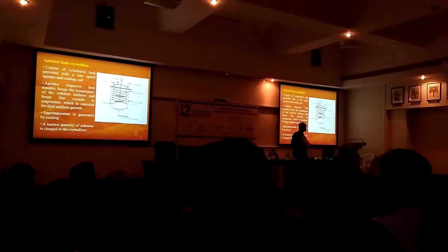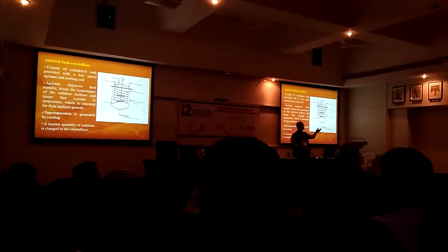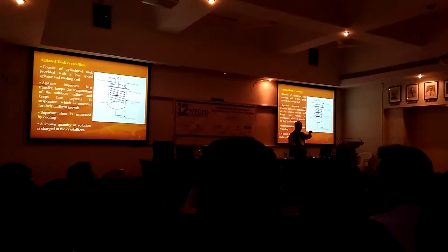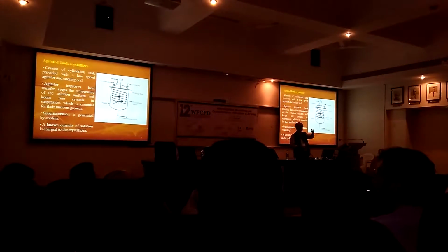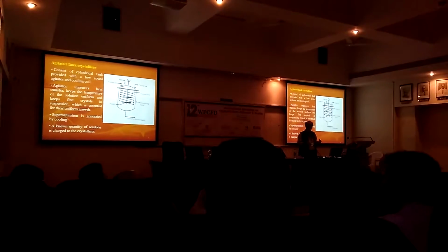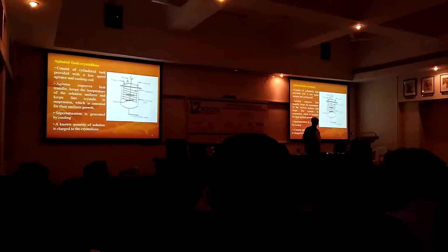You can find what the requirements are in here. You have an agitation. Why agitation? To keep the solids in suspension so that all the surfaces of the crystals are available for the deposition of the solute. The rate of growth of every surface will depend upon thermodynamics, as was pointed out, and the crystal will not necessarily grow in the form in which we want, and we will talk about that a bit later.